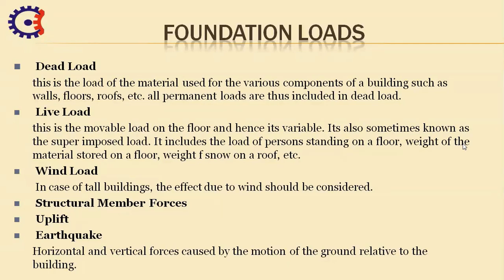Next is live load. The weights in the structure may be assumed as live loads if they are temporary during the service life. For example, human occupancy, some partition walls, furniture, some stock material and mechanical equipment in a residential and office building are live loads. Next is wind load.